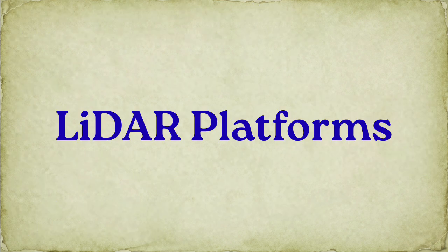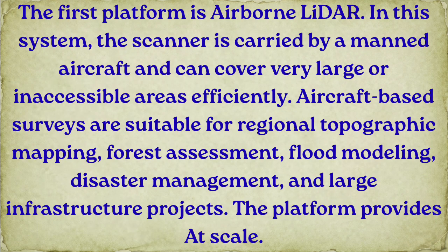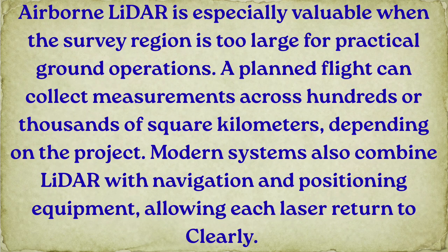LiDAR platforms. The first platform is airborne LiDAR. In this system, the scanner is carried by a manned aircraft and can cover very large or inaccessible areas efficiently. Aircraft-based surveys are suitable for regional topographic mapping, forest assessment, flood modeling, disaster management, and large infrastructure projects. Airborne LiDAR is especially valuable when the survey region is too large for practical ground operations.